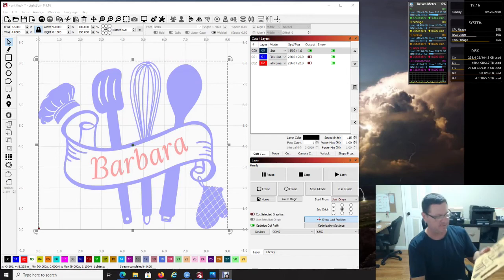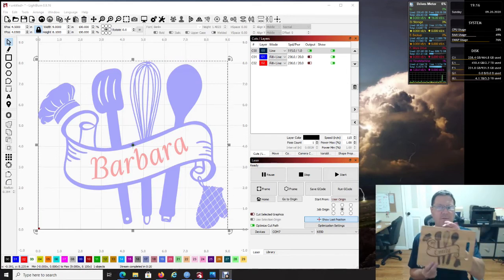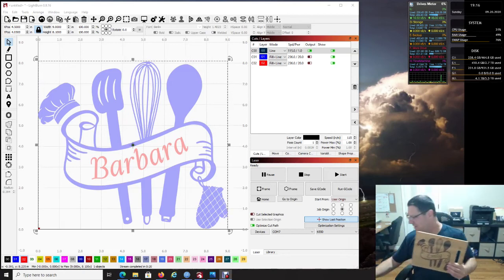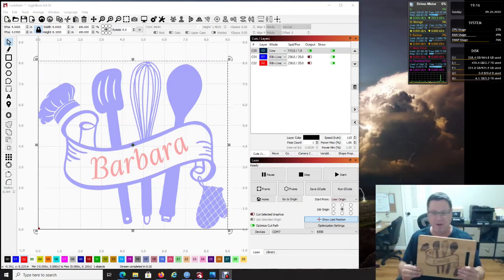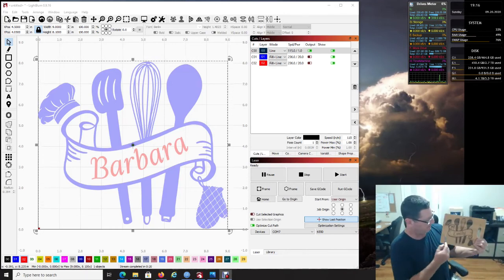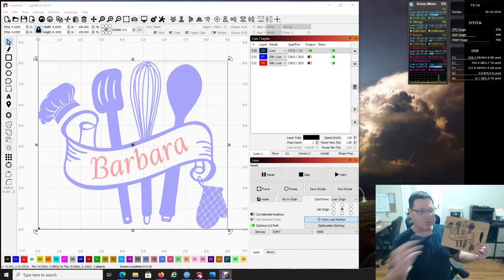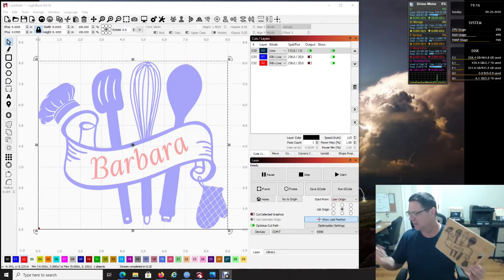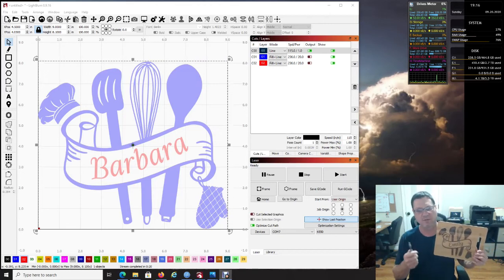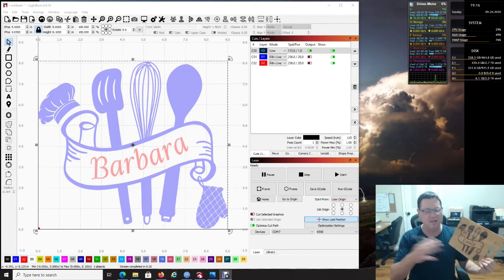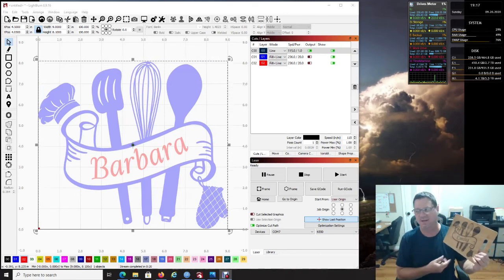The reason why that's important is because on all of my stuff that I do, I do everything that I cut and I burn, I make sure that I measure the outline, and then I do all my work within that outline. And that's how I get almost a perfect burn every time. It's worth that extra couple minutes. It's worth the extra time to put it at 1% power and run your frame around it. And no matter what I do inside that, I know I'm not going outside my burning area.